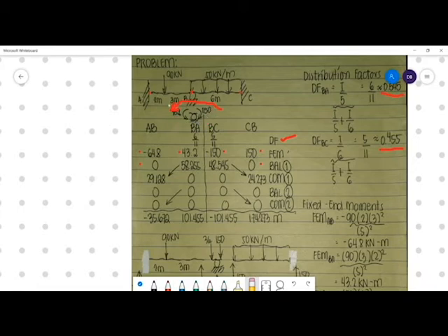Okay? So that is the balancing moment, which is equal to the resultant of our 43.2 and the 150. Which happens to be negative 150 plus 43.2. Okay, that is negative 106.8. So it is clockwise, so the balancing one is counterclockwise. With respect to the joint, the resulting moment is clockwise.